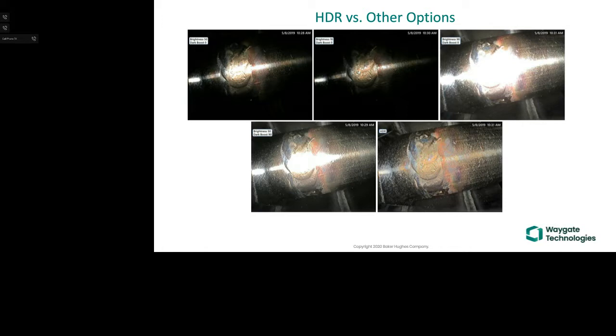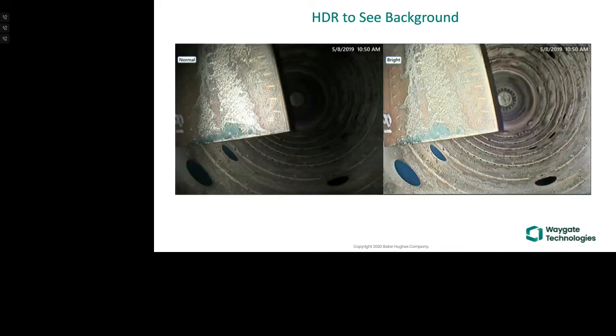Here's an example of what that HDR image would look like. This is a JT8 burner can. The fuel nozzle's down at the far side. This object was stuck into the path just so you know that sometimes images close to the camera are going to be brighter, and the camera adjusts for that, and so you can't see past it.